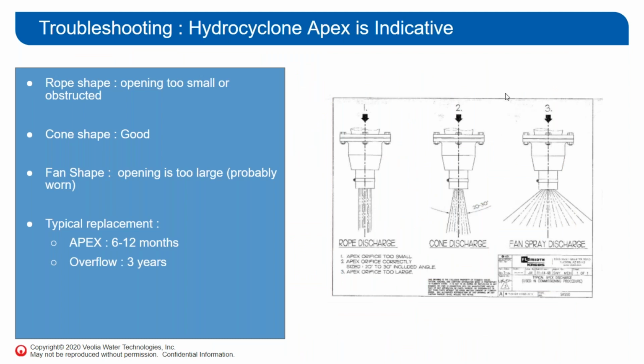Getting back to the hydrocyclone, just because it is such an important aspect of your troubleshooting, a good cone discharge is something you identify visually if it's the type of hydrocyclone that isn't set right into the surface of the tank. Not only can you see this good medium level cone, but you can hear it frequently enough, especially if you're walking past hourly.